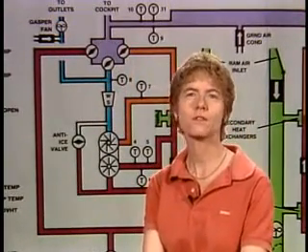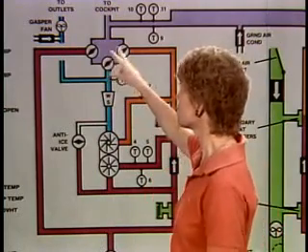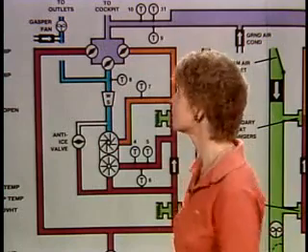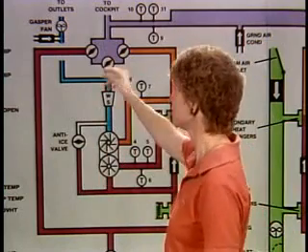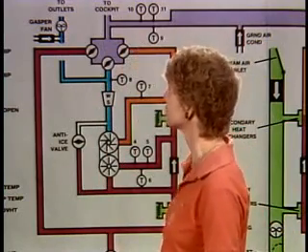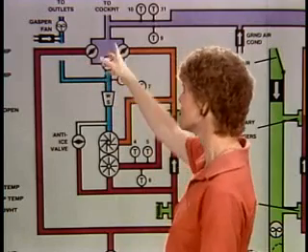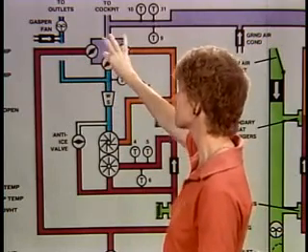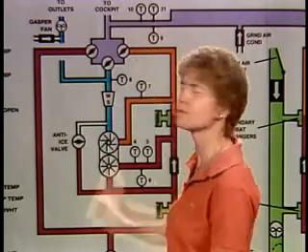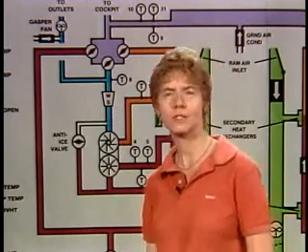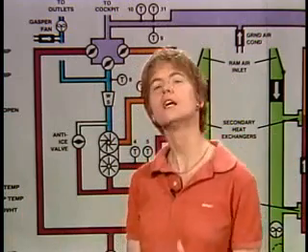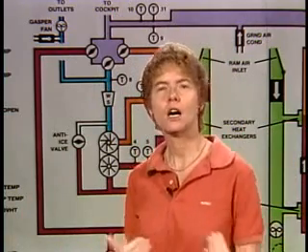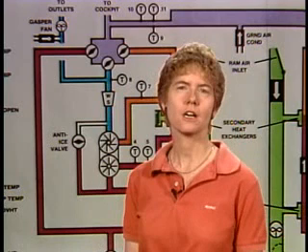The purpose of that mix valve in the air conditioning system is to control the supply of hot, cool, and cold air, because it's got cold air, it's got medium temperature air, and it's got hot air going into it, and the various valves mix them in order to get exactly the temperature of air that you want based on how the mixing valve is set. Okay, that's basically the air cycle cooling system in an aircraft.